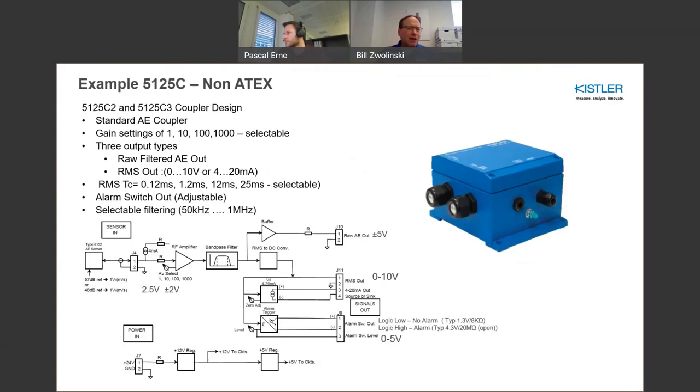So how is this thing powered, and what does a measuring chain look like? Well, an AE sensor is typically, not unlike an accelerometer, an IEPE style of sensor, but it's not operating like an accelerometer. Its bandwidth is super huge, so you can't really use a traditional accelerometer power supply to power this.